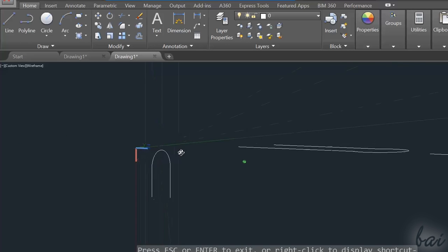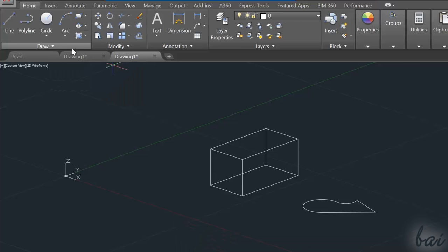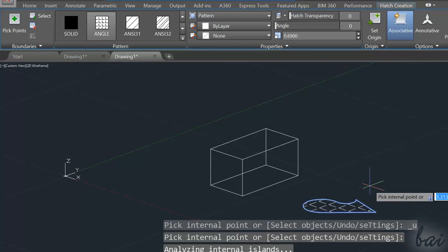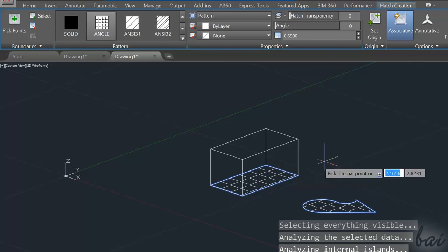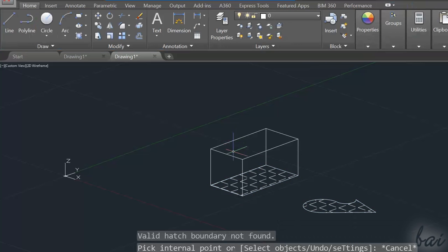This is not the only problem with 2D tools. Even more, you can't use the hatch command properly inside a 3D environment, since this works just on a closed path that lays completely on the XY ground plane or any plane parallel to it. Plus, this does not fill any 3D volume at all.